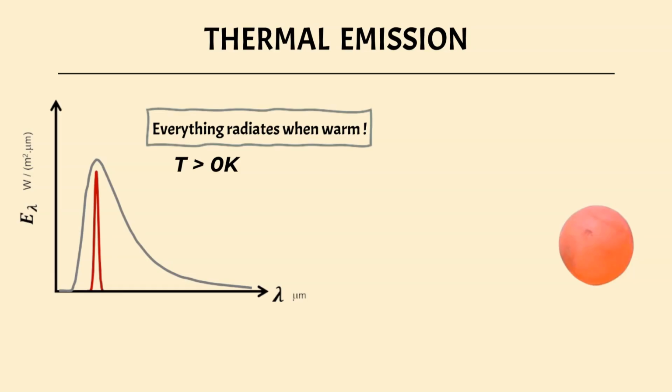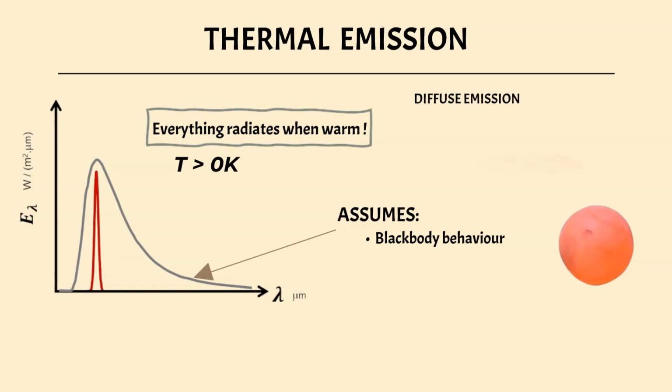A material's appearance can hint at how it behaves thermally, since reflection and emission depend on how surfaces interact with different wavelengths. An idealized reference is referred to as a blackbody. A blackbody absorbs all incident radiation and emits thermal radiation diffusely, that is, isotropic in all directions, with a spectral distribution that depends only on its temperature.